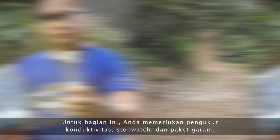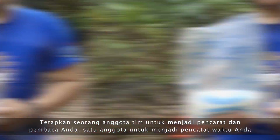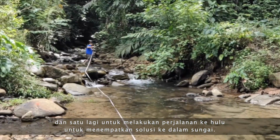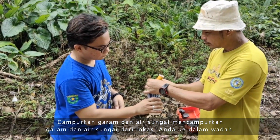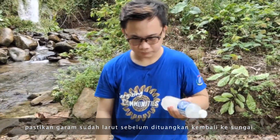For this section, you will need your conductivity meter, stopwatch, and salt packets. Assign a member of the team to be your note-taker and reader, one member to be your timekeeper, and one to travel upstream to place the solution into the river. Pre-mix the salt solution by mixing the salt and river water from your location in a container. Ensure the salt is dissolved before pouring it back into the river.